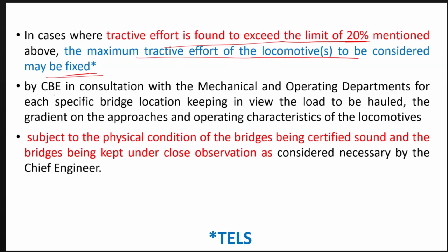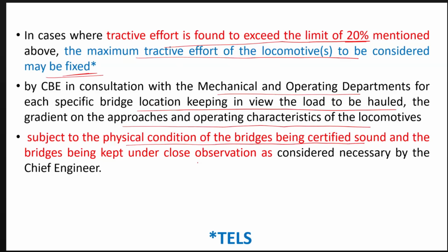It is fixed by the CBE in consultation with the mechanical and operating departments for each specific bridge location, keeping in view the load to be hauled, the gradient, approaches and operating characteristics of the locomotive, subject to the physical condition of the bridge being certified sound and the bridge being kept under close observation as considered necessary by the chief engineer.